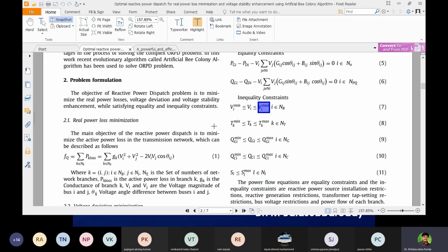That is one thing. And tap changing. I told you in HVDC transmission also, before the converter and after the inverter, there are tap changing transformers. Why these tap changing transformers? To adjust the voltage, to maintain it as a constant voltage or to keep it within a limit. For that, taps are also available in a power system. Some tap changing transformers are also there.